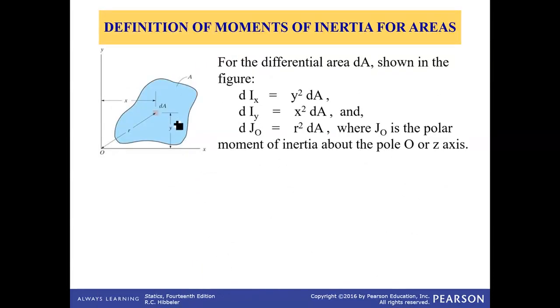Now the formula for moment of inertia calculation is, let's consider that for this irregular shape, we consider a small square portion with area dA, which is located at x units from y-axis and y distance from x-axis, and in polar coordinates its distance is r from origin. So its area moment of inertia for this shape can be calculated using y square dA. From the x-axis, the distance is y, so y square multiplied by area. That is called the x AMI.